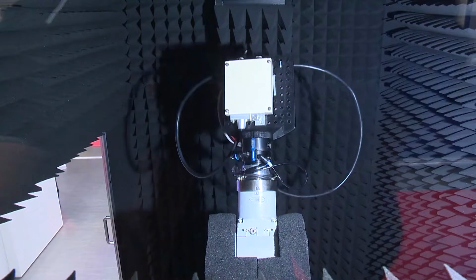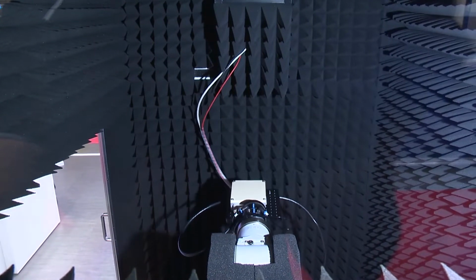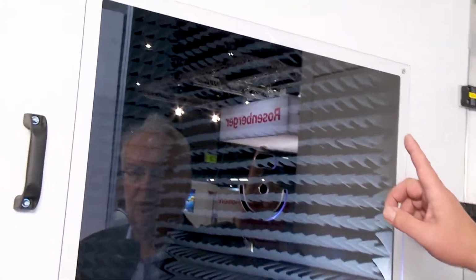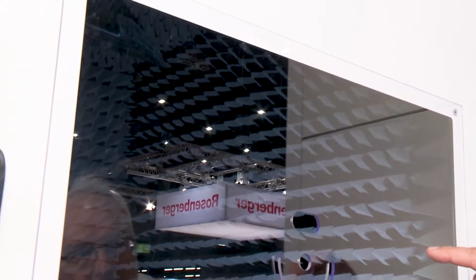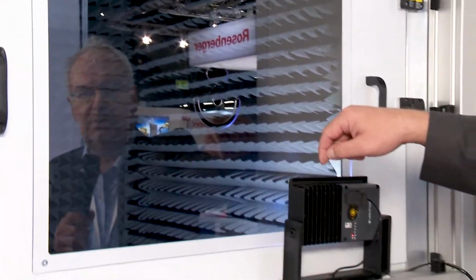There is the radar under test held by a robot. And up there in the ceiling of this chamber is a mirror that reflects the radar waves from the antenna down to the system under test. And this setup enables far field distances in this very compact chamber. This would otherwise, for very modern radar, require very huge test systems, 7 meters long, 8 meters long, about that, because these radar systems need to see far field conditions when they are tested. So this is what we have here.